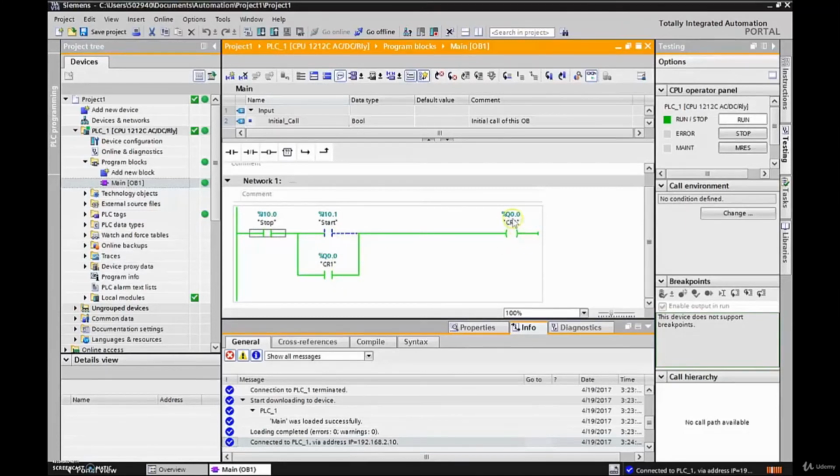There we go. So now we've got a green check mark here. We are talking to this guy, and we're connected into the PLC, and you can see that this is connected into the stop push button. Now I have all of my push buttons open right now, so I'm going to close the stop push button right now. Okay, so again I'll close this stop push button. There we go. So you can see that as I change my stop push button, then it changes real time